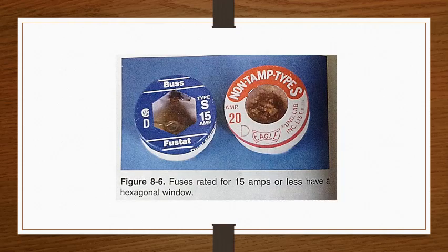Plug fuses are limited by the following voltage restrictions: a maximum of 125 volts between conductors, and a maximum of 150 volts between ungrounded conductors and the ground in grounded neutral systems. Edison-based fuses are interchangeable. Fuses of greater current rating can be used in circuits of lesser capacities.